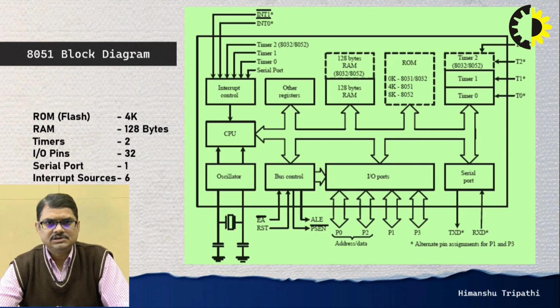One section is the user RAM that as a programmer we can use to store any data as general program or data memory, and another 128 byte memory is reserved for some specific purpose. That specific purpose memory, or special function memory, is also referred to as special function register space.